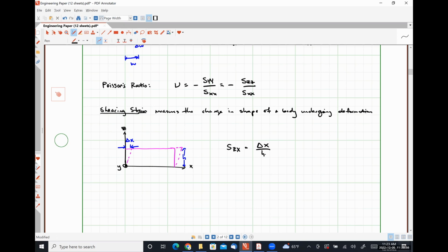So another way to think about the shearing strain is that it represents the extent of a rotational displacement, right? So if we had a beam and we push on this surface, we are going to try to rotate it forward. Or if we have a cantilever beam and we're applying a point force down, we're going to try to rotate the tip. Okay, that's all shearing strain is associated with.